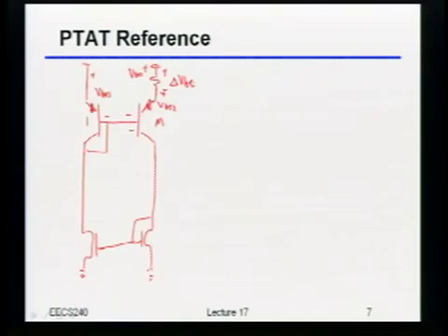Okay? Well, so as we're going to see in 1 second, by using some clever tricks of logarithms and etc., delta VBE is going to turn out to be proportional to temperature. Okay? So the way to see that is just to remind ourselves, let's say I had a BJT or even a diode or something like that.